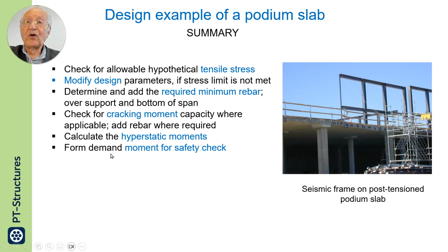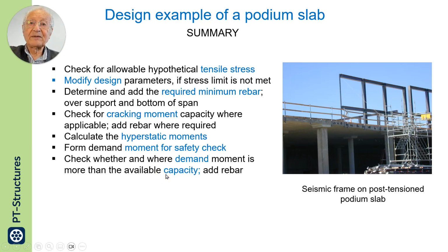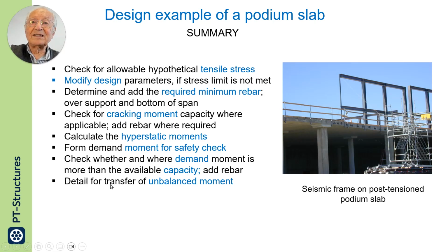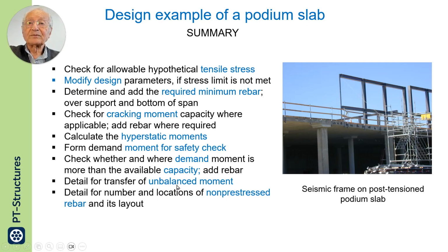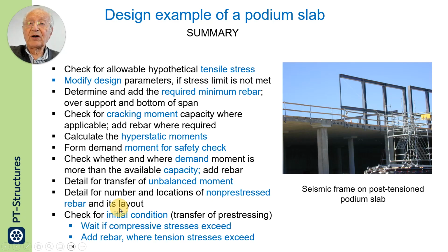We formed the demand moment for safety, which includes the hyperstatic. We checked whether the demand exceeds the capacity, and where it exceeded, in our case it did not, you have to put rebar. And then we went into detailing, which included unbalanced moment transfer, and then detailing of non-pre-stressed rebar.